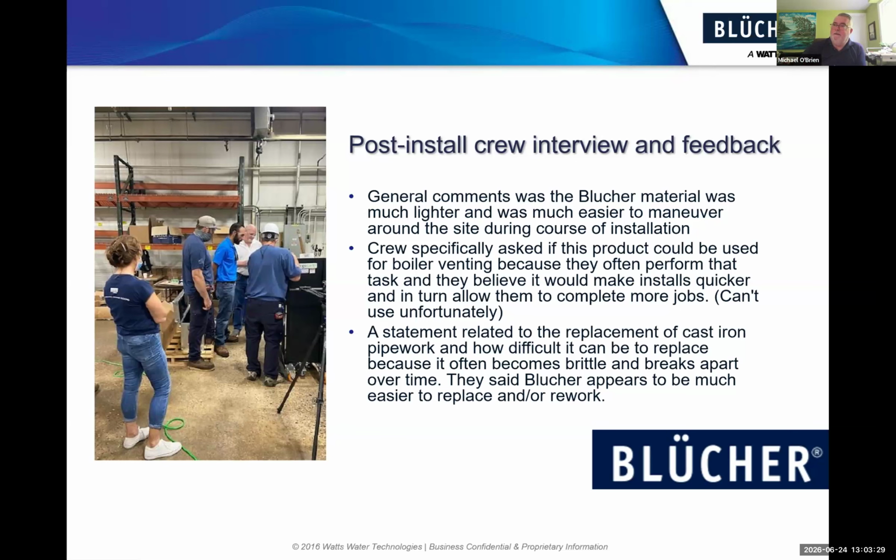If you had a vertical section of pipe in all three materials and a forklift backed into it, the PVC and the cast iron would crack and break apart and become a critical fix. If you back into the thin wall stainless steel, it's definitely going to dent, but it's still going to be sealed. It's not a case of, okay, we have to stop everything we're doing to get it replaced. It's a case of, okay, this needs to be fixed, and we can do it when it's convenient. We can continue to produce what we produce.